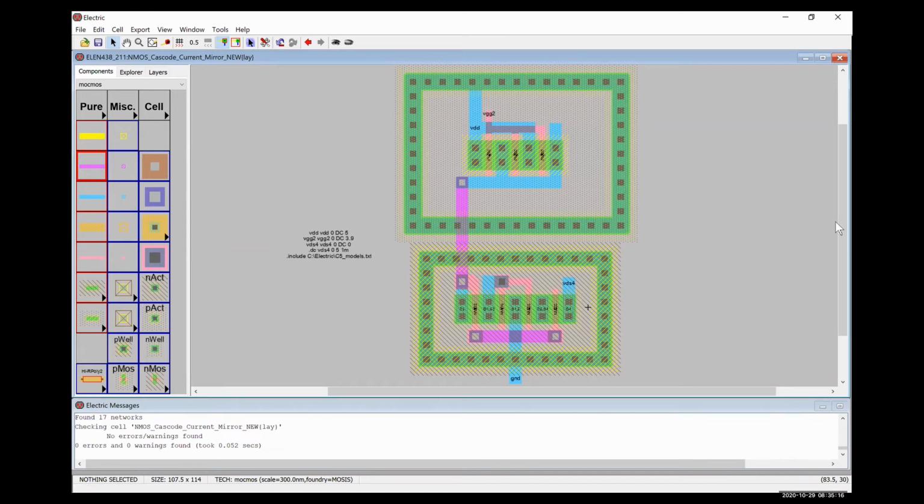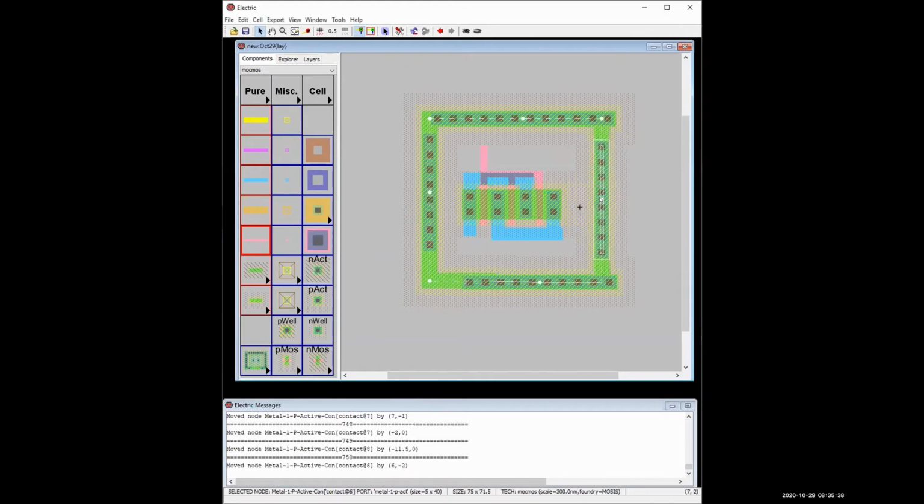All right, so we're getting close to finishing up that topmost bit. I hope so. I'm still getting a lot of errors. Show me what's going on, Grant. All right. Can you see it? So the issue, I think, is that you're connecting the active regions and not the metal of the grounding ring. Yes, okay, that would be my best bet.